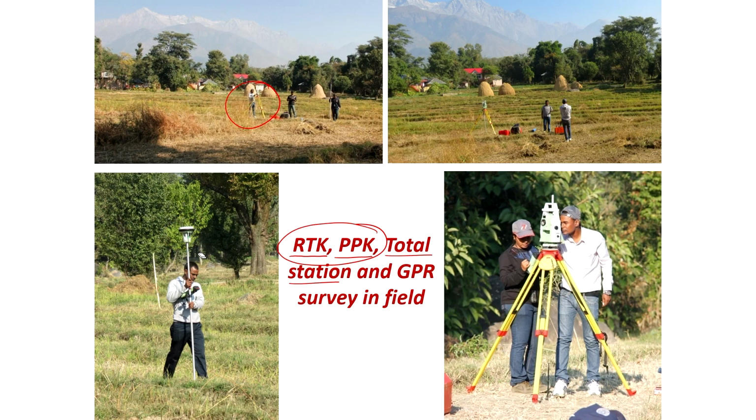Another important point here is that you need not stop and stay to collect the points of your desired area, but you can keep moving. You can set up the timing for what interval you need, 5 seconds or 1 second, or you can decide that.